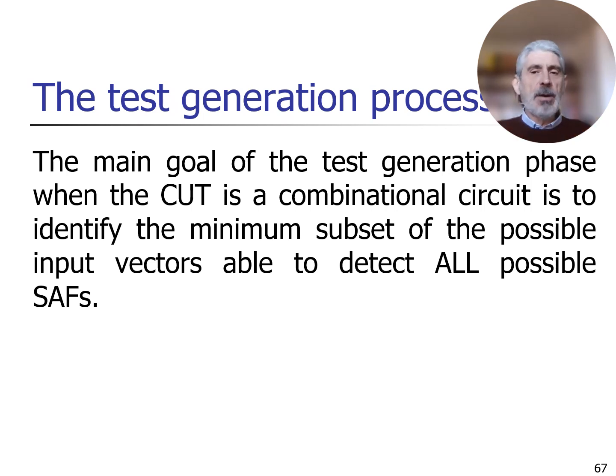Now, the general problem, however, is not simply to scan the list of possible stuck-at faults and for each one of them to generate a test vector, so that if there are m faults, we have m test vectors. Why? Because this is a waste of time, because every vector, as we just saw, is able to detect typically more than one stuck-at fault.